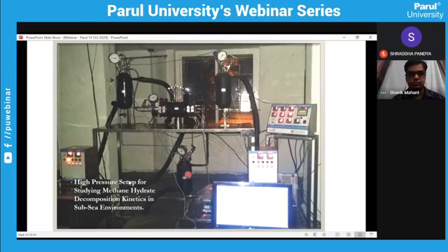And in this vessel we can store hot water. So once the gas hydrate has formed, we will send hot water into it. Like thermal stimulation, we will separate gas and water from the gas hydrate, and then the gas will be stored in this. So this is one step of technology development of gas hydrate production. Sorry, natural gas production from gas hydrate.